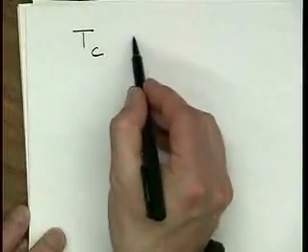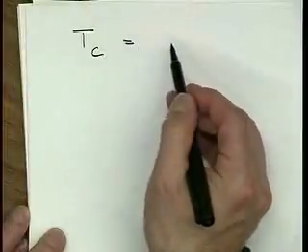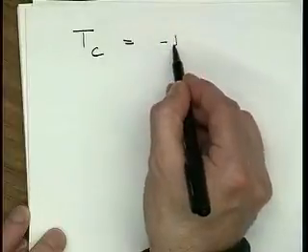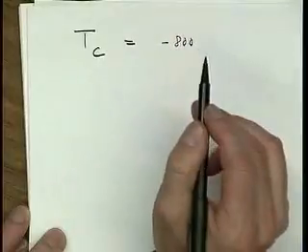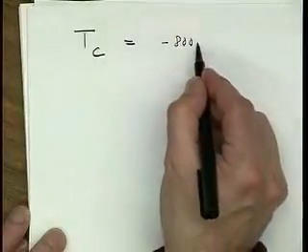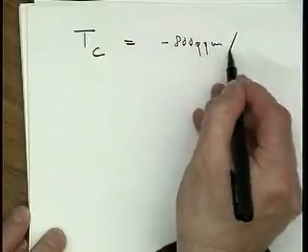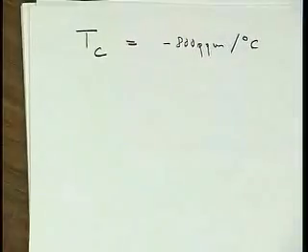First of all, the temperature coefficient for a resistor is described as a TC, for example minus 800 ppm per degree C, and it can be positive or negative. In other words, a resistor changes by 800 ppm, or just a little bit less than 0.1%, for every degree.